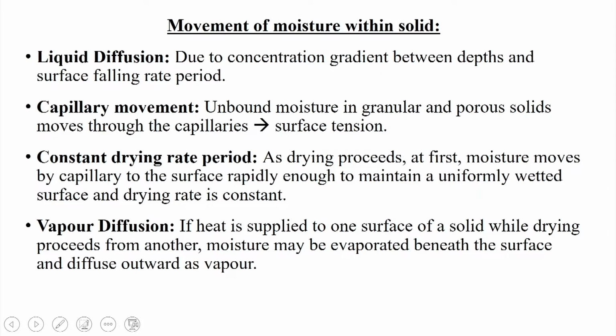In the constant drying rate period, as drying proceeds, at first the moisture moves by capillary to the surface rapidly enough to maintain a uniformly wetted surface, and the drying rate is constant. So we can say, by capillary action, the water moves from the interior of the wet solid to the top surface of the wet solid.